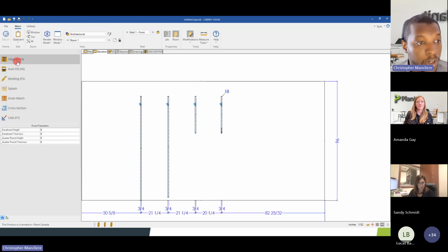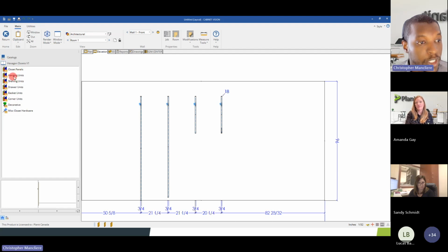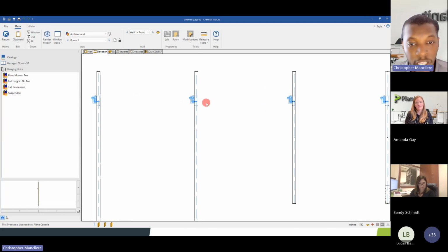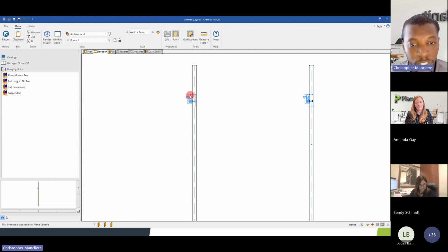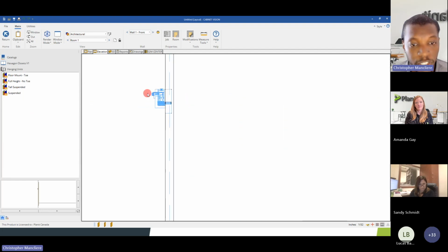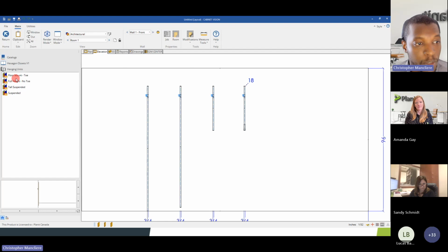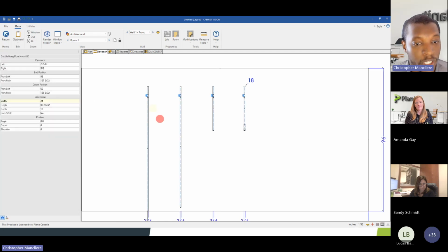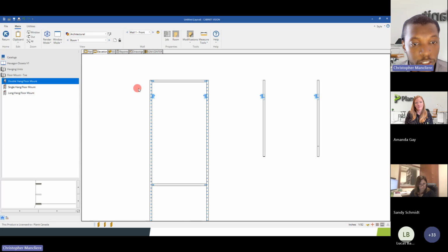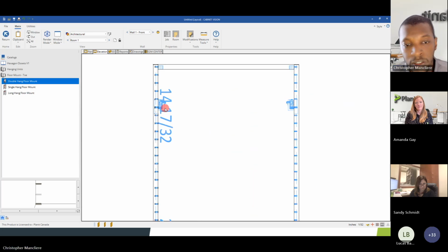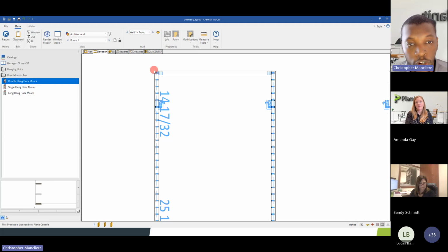And then you have a lot of different units. You have hanging unit, shelving unit, drawer unit, basket unit, and corner unit. We'll use them later when we do a live demonstration, but just to use one quickly to show you what happens. Right now I just have my panels. Cabvision is always waiting to create the machining for the hanging rail, but it doesn't know yet on what side to do it. So by default, it will always appear on the left. But if I just drag and drop a hanging section, automatically my hanging notch will be inside, and also all my machining will be applied.